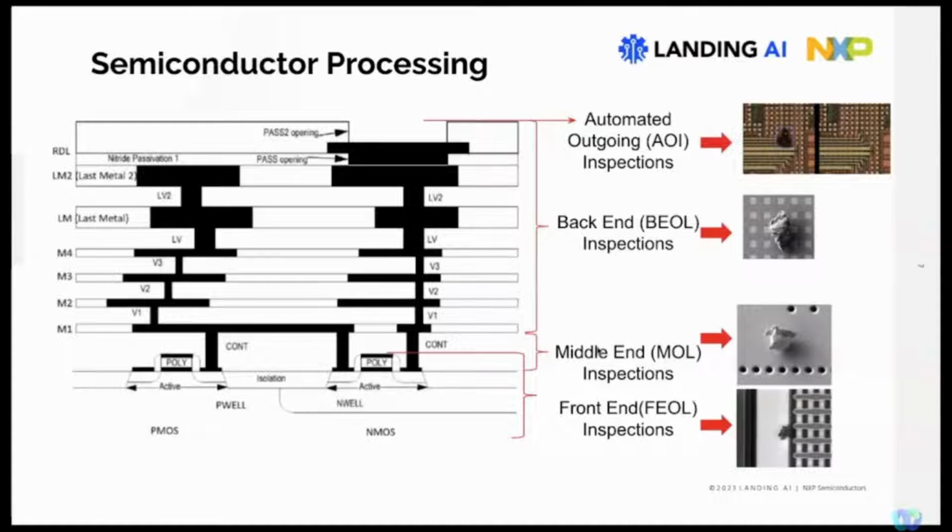And you can see on the colorful optical images, the reference versus a defective die, you would actually reject this die. Even if you didn't detect the defect up until that point, this will be the last point before the chip is sent to other sites to get packaged and electrically tested. So before this point, there is no electrical test, but after this point, the chip is sent to a package, and then electrically tested, and then either rejected or not rejected.